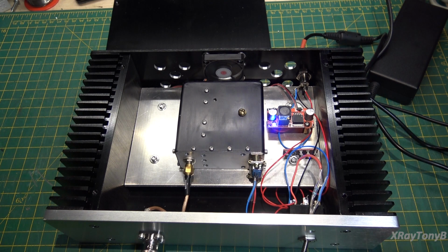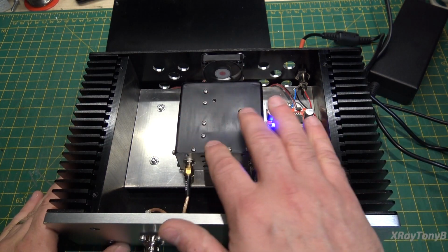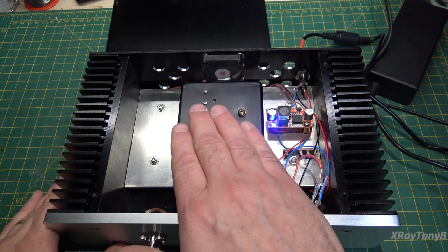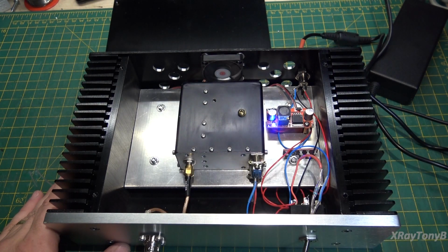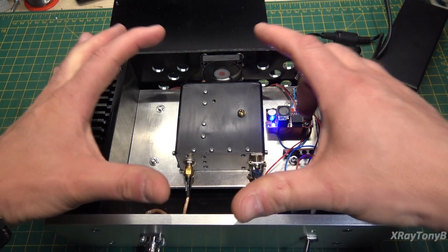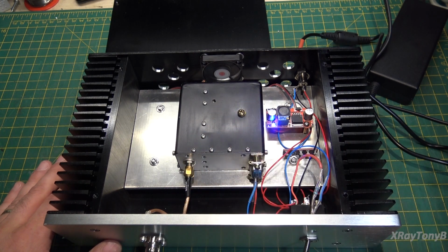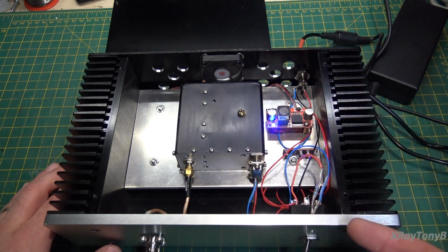And if you want to build one of these, that's really all there is to it. The only thing you have to watch when you order these, there are several different models out there. This is the less common one. The more common ones out there are a little bit bigger. They almost look like a hard drive out of a computer, size-wise. They all do the same thing, but you have to be sure that whichever one you buy actually has a 10 megahertz output, because all the test equipment uses a 10 megahertz reference signal. And you got to watch, because some of these put out 15 megahertz or different frequencies.